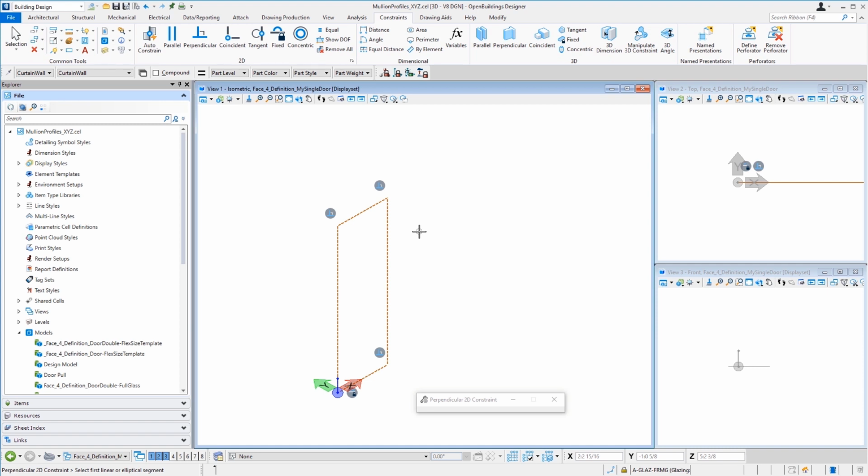Now we're going to start setting up some geometry for the actual door. So this door is going to have a frame, top and bottom, and then glass in between. It's a fairly simple door. And I'm going to first create some 2D geometry, and then we'll extrude that geometry to create the solids we need for the 3D geometry. So again, I'm going to use the Place Line tool. First, let me match my attributes there, and we'll do the Place Smart Line.